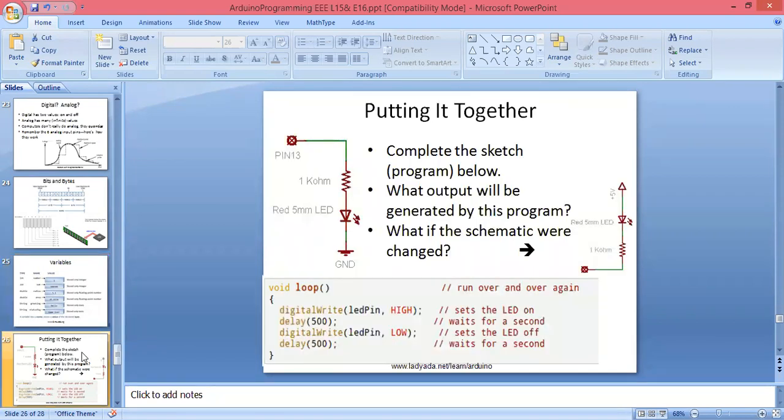If we are supposed to do a program for an LED, how will we interface? Firstly we will take the Arduino Uno board, and we will connect digital pin number 13 to the LED. How will you connect? We know this side will be considered the anode, and the side with the arrow will be considered the ground. We can connect pin number 13 to the anode of the LED by using a resistor.